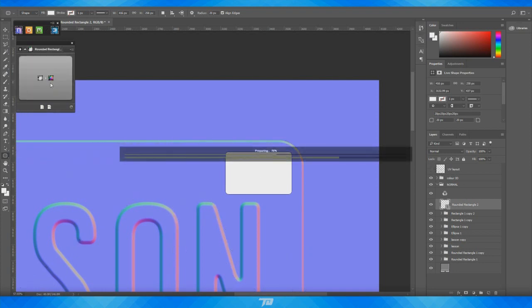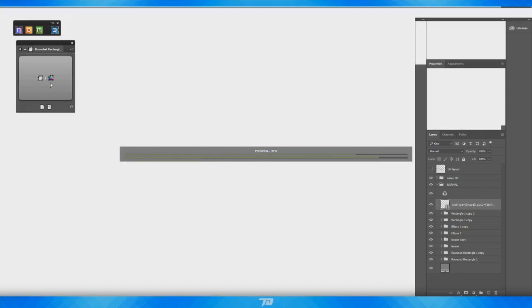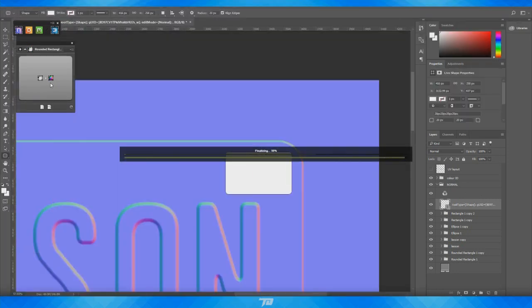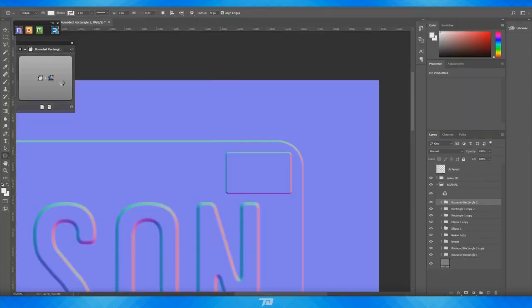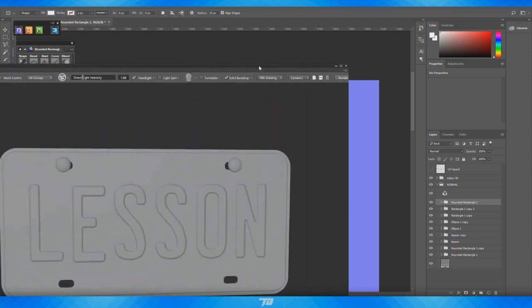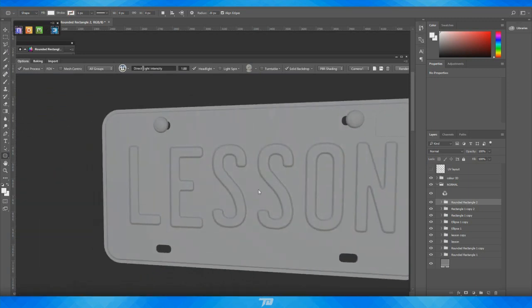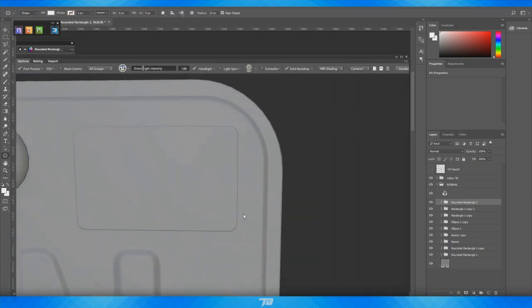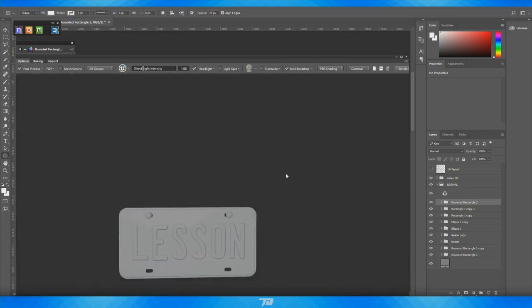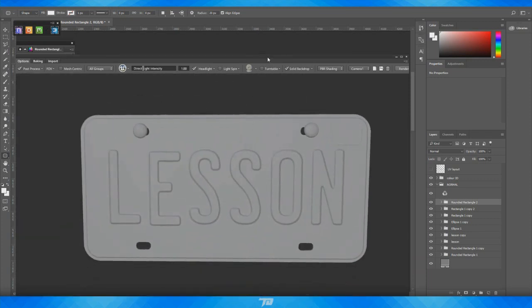I'm just going to convert that by pressing the big button. And since it's just a sticker that we're working with here, it's going to be super simple. It's essentially just going to be the way it is, just with a tiny normal map on it. Like something like that. And if I hit refresh, we can check it out in the viewport now. Essentially we just have this tiny sticker on there, which is exactly where we want it to be. It's how it's supposed to look. And a sticker would still sort of have an edge on it, so that's why I normal mapped it, but it's super subtle. And that's just the way I want it to be.